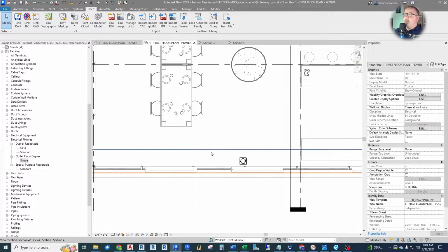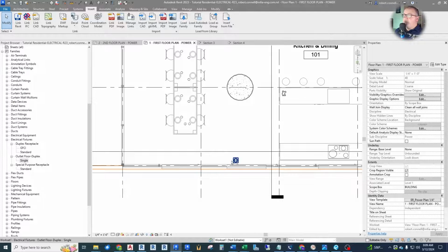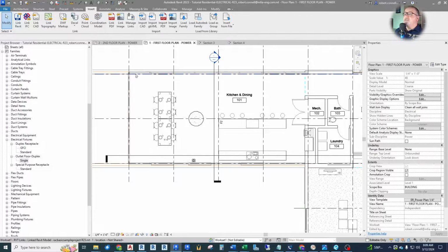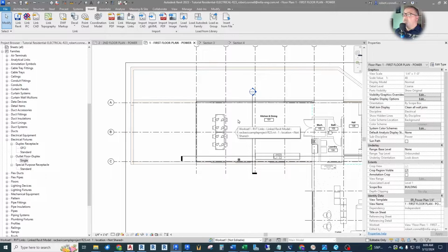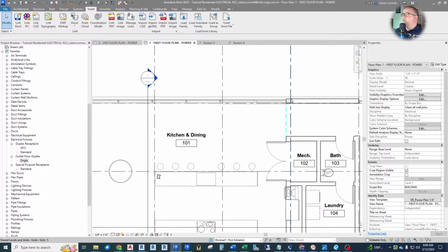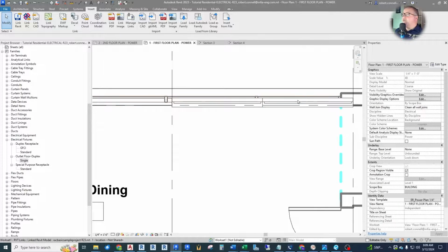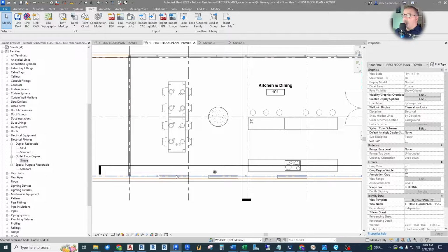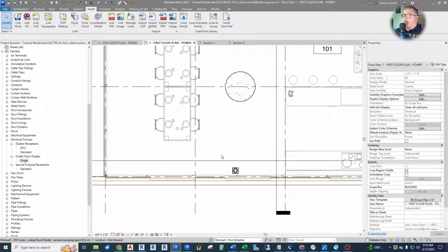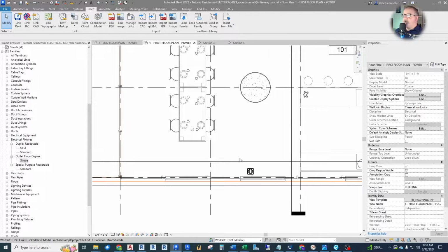Let's go to the next one and keep moving along. In general, we're going to be measuring not more than 12 feet along here. I don't see any operable doors out of this first floor, so we don't need to worry about watching out for doors. So we're going to go all the way around this with our receptacles. So I'll end up speeding this up so you don't have to watch every measurement.